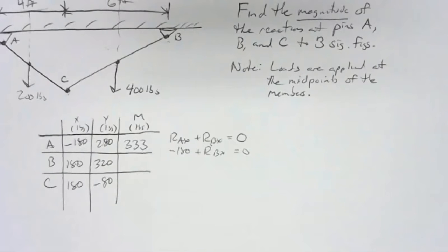If we knew something about the diameter of A, we could talk about the shear stress involved. And that's the part of the course we're going into next, looking at the materials and how much stress is involved and whether this thing could handle it. This is a 1/4-inch nail, or a number 10 nail, or a 6-penny nail, something like that. Is this going to handle that stress, or is it going to shear out?